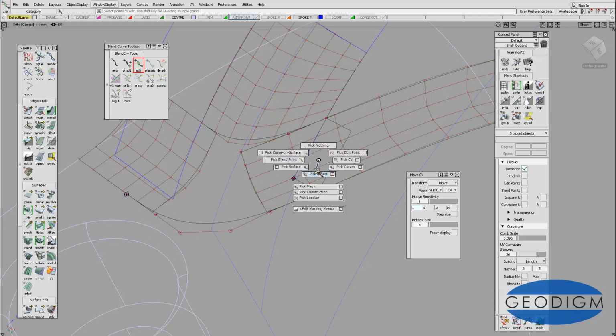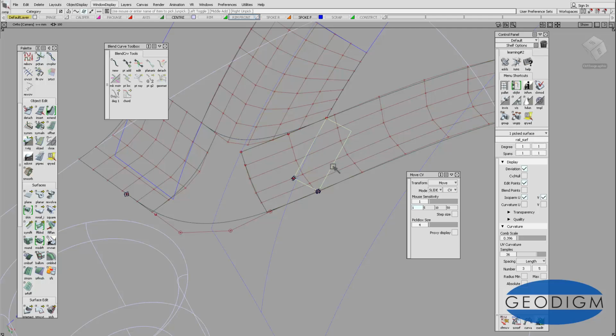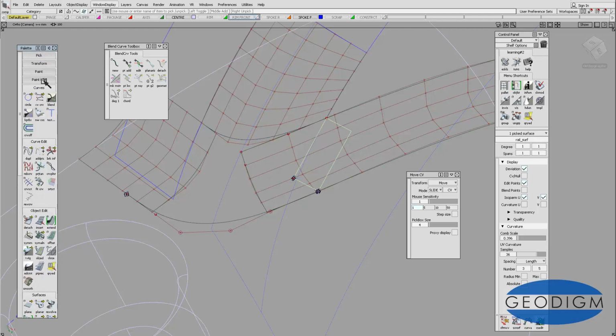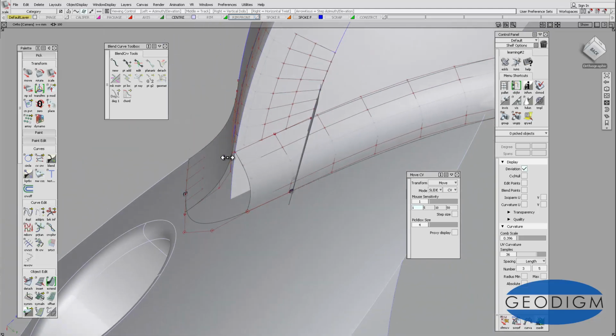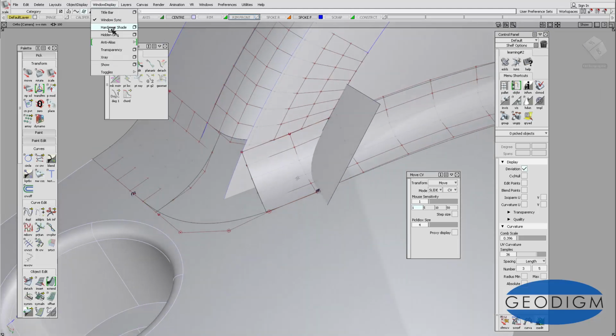A simpler way to do it is if we pick that surface and we go into the Transform tab here. Under the pivot options there, we've got something called center pivot. What that does is put the pivot point right in the middle of the surface. And so now we can go and scale that. It's going to break the construction history now, but we can scale that up, and we've now got a patch, a surface, which is intersecting that fillet completely. So there's no doubt about that.